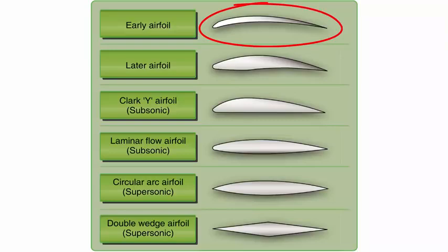As a fixed design, this type of airfoil sacrifices too much speed while producing lift and is not suitable for high-speed flight. On the other hand, an airfoil that is perfectly streamlined and offers little wind resistance sometimes does not have enough lifting power to take the airplane off the ground. Thus, modern airplanes have airfoils that strike a middle ground between extremes in design. The shape varies according to the needs of the airplane for which it's designed.